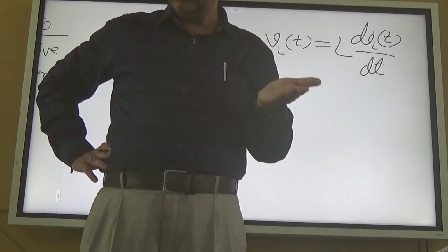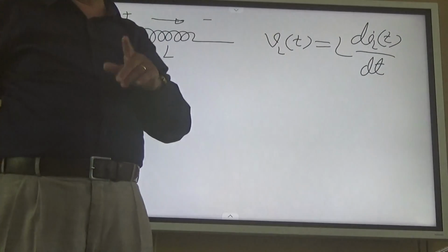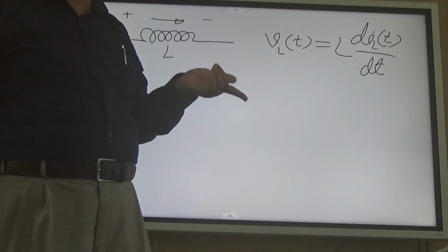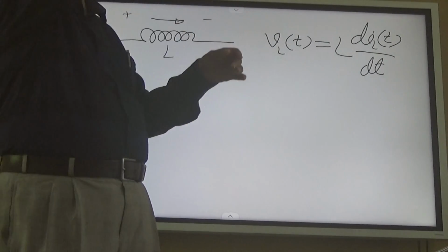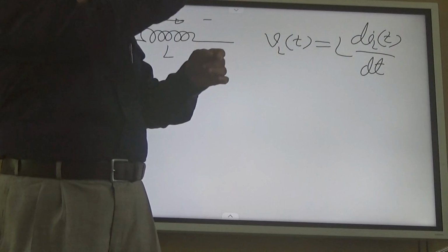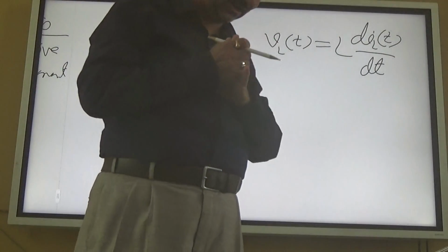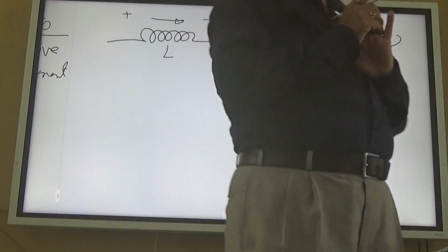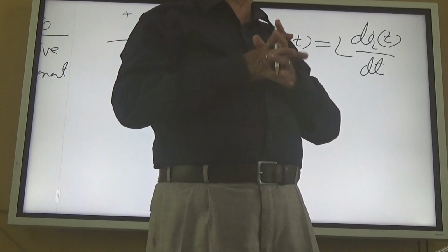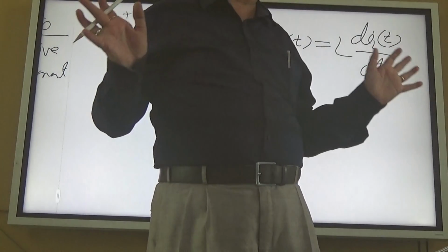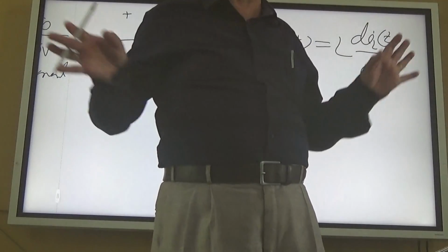Current is proportional to the differential of voltage. To be very classical, using the term current through capacitor is wrong. Current is not through the capacitor. It comes in from one end, goes out from the other end, and does not cross over. But anyway, we don't give much significance to that now. So we can say current through capacitor, or capacitor current, is proportional to the differential of voltage across the capacitor. That's what we understand to some extent and we know fully.